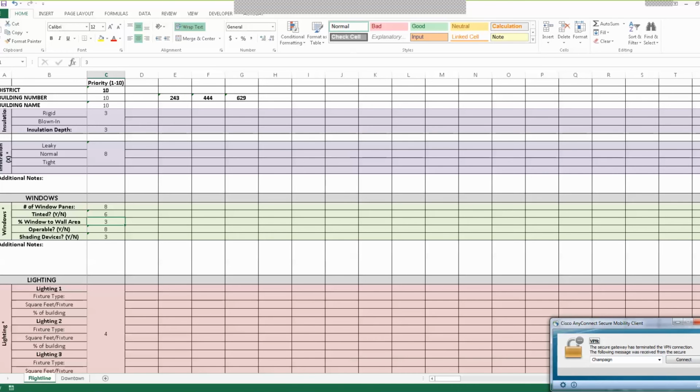On a big building, if you think about where you want to put your energy, and you're looking at the envelope of a big building, and let's just say it's standard construction, it's got a fair amount of interior space compared to the envelope, so the building's not going to be envelope driven, right? So when you get to smaller and smaller buildings, all the way down to residences, then it becomes more envelope driven. So we want to put more emphasis on the envelope as we get smaller and smaller.